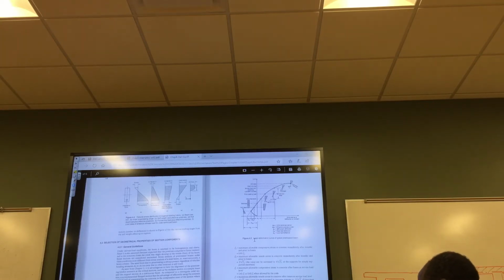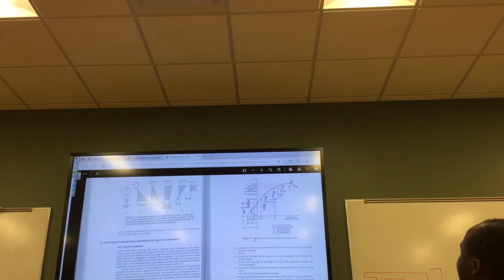There's a thing in steel design, in bridges, Barry must know this, that you put a girder with a camber for the same reason, so that when you put the load on the bridge, it will balance out and not sag as much because you're pre-cambering in the opposite direction. We are doing the same thing. We are cambering up, and whether you like it or not, the self-weight is going to work down. So the self-weight comes on as soon as you apply the pre-stress force, whether the beam is sitting on two supports or on a flat surface. Both cases, it will camber up and camber back down.